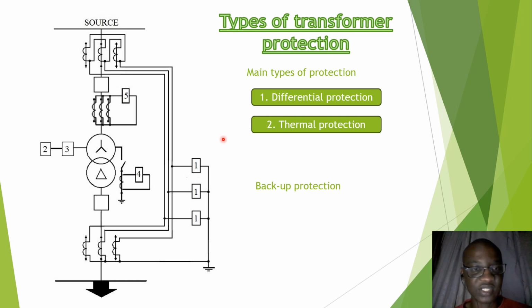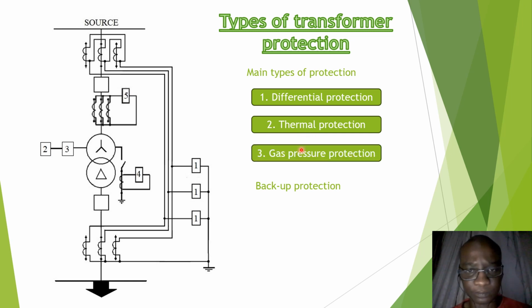So for this reason, we place temperature sensitive devices in the transformer to monitor abnormal rises in temperature and trigger the thermal protection to protect our transformers.